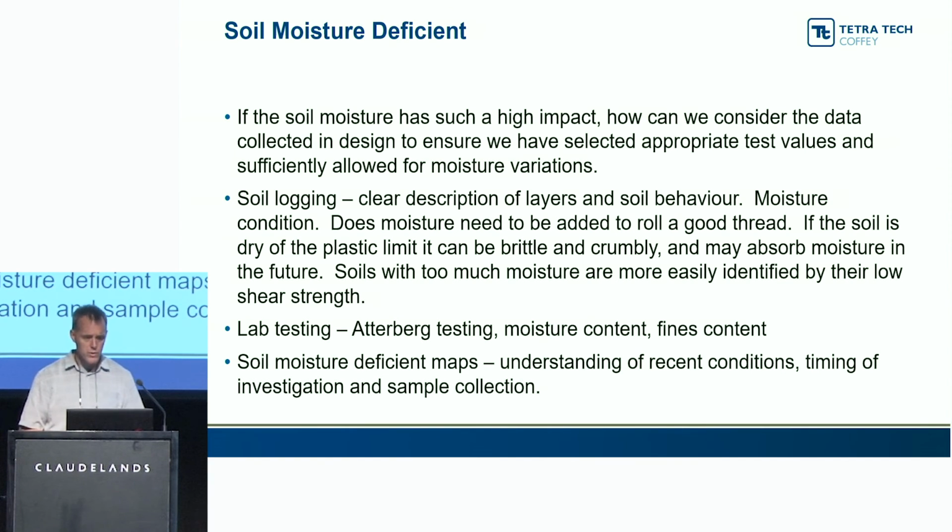Also understand your moisture history. If you're working locally, you know what the weather's been like. If it's been really dry for 2 months, maybe it's not a great time to go out and do your testing. If you've gone up to Hawke's Bay to do some testing and it's been dry there, you should at least ask the local contractors what the weather's been like and get an understanding of it.